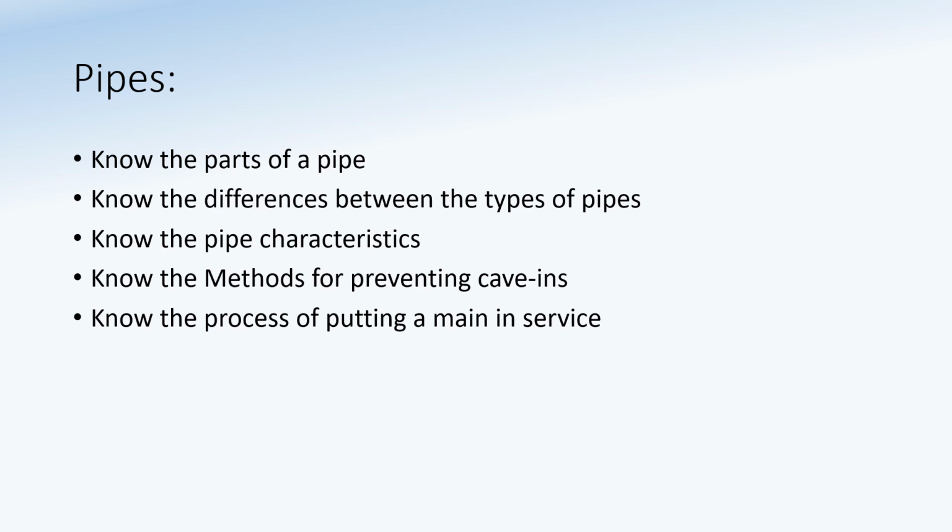Know the process of putting a main in service, right? So you got to pressure test it, you have to chlorinate it, you have to pass bacteria tests. All of these things need to be done before placing a main in service.